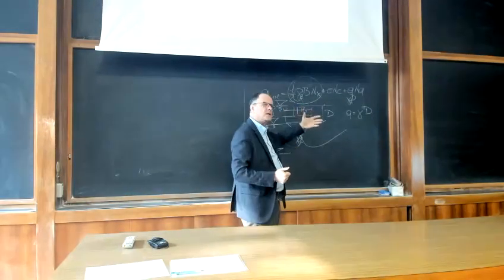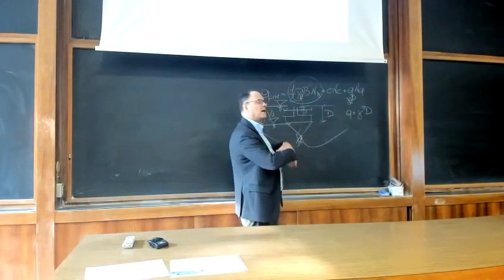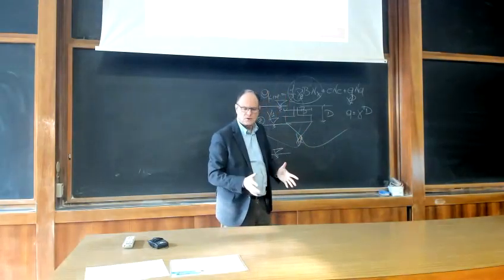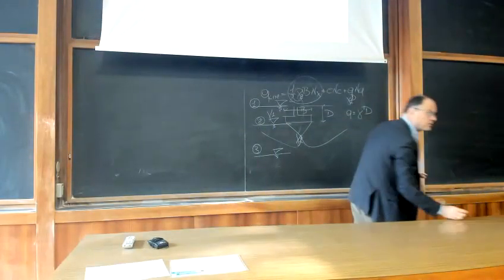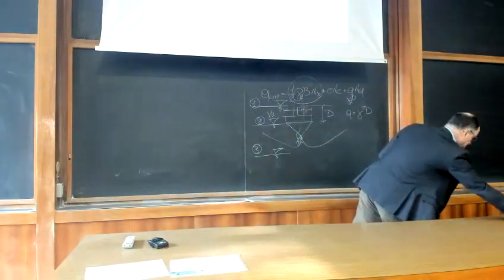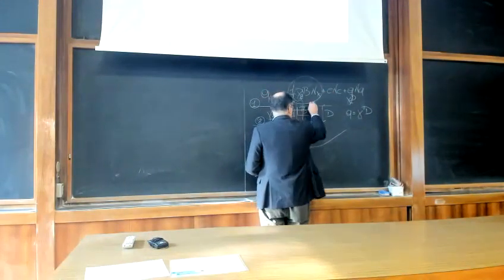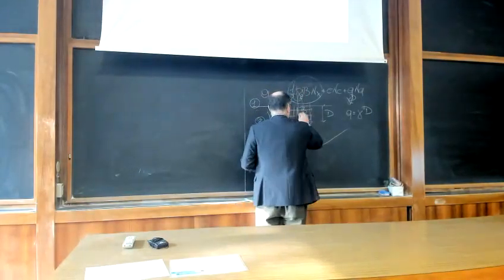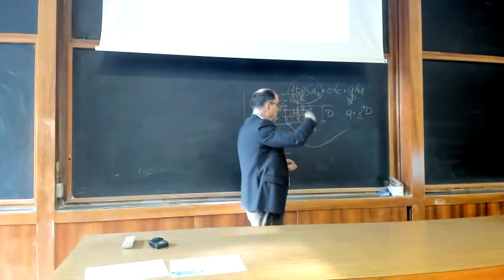Because remember, we said this is for applying the limit equilibrium or the upper bound theorems, so we distinguished and separated drained and undrained conditions. But in any case, in this formula, we have made also other assumptions. For example, that the load is vertical, distributed. The resultant here, Q, is centered and vertical.